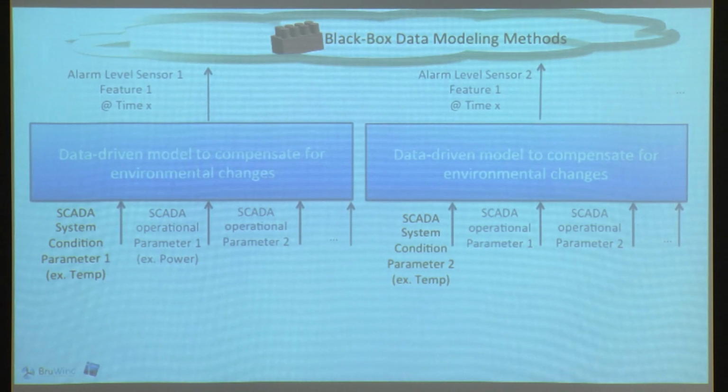This allows you to see when the temperature starts going up or when it starts behaving very strangely under different operating conditions. We use this as an alarm metric, again, as a feature to detect when something is going wrong. You tend to see that a bearing gets heated more and more when it starts to have more metal-to-metal contact or when it starts deteriorating. So it's a very nice metric to detect again that something is wrong.